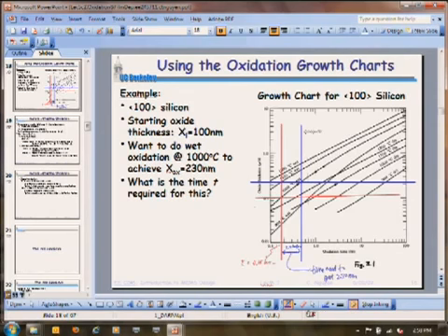Did you have a question? Yeah, this seems kind of approximate, though, because you put it in for 20 minutes. Yeah, that's true. But everything is approximate in the end. So for example, when you're working in the lab, my wanting 230 nanometers may not be that reasonable. Because even across the wafer, maybe some parts will be 230 nanometers, but others may not. Right? So there's variance in all of that. So it makes no sense to be too accurate about it. You can chug into the equation and get a very accurate answer, but in the end you'll do no better than this because conditions change.